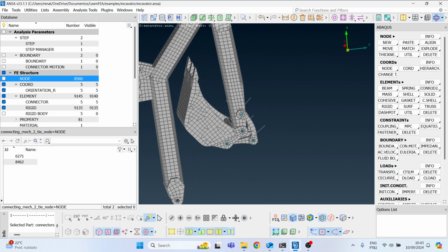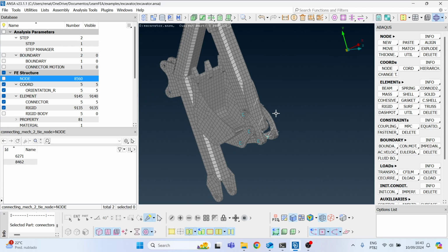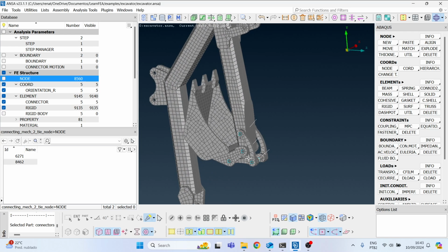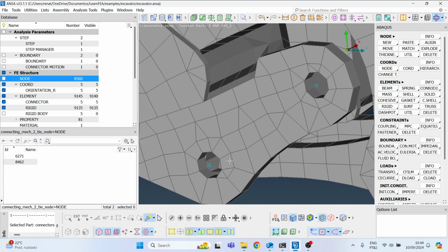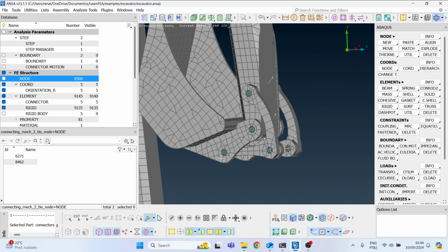Now we have everything connected, but I don't think this is going to work because the hinge connector creates over constraints if everything is not perfectly aligned. If there is a little disalignment between the x-axis of these hinge connectors, then we are going to face an issue. And this disalignment can be caused because of the CAD, okay? Because the CAD may not be so perfect. And remember that we had defined the axis direction by using these points that we created on the COG of each circle.